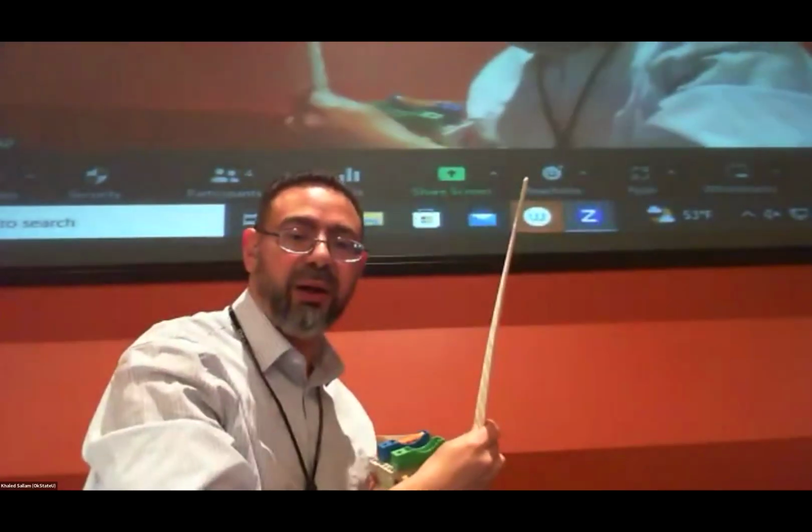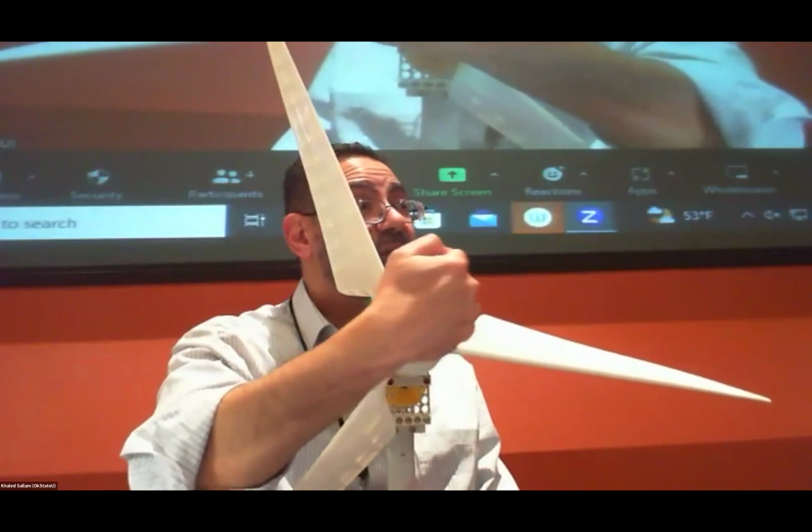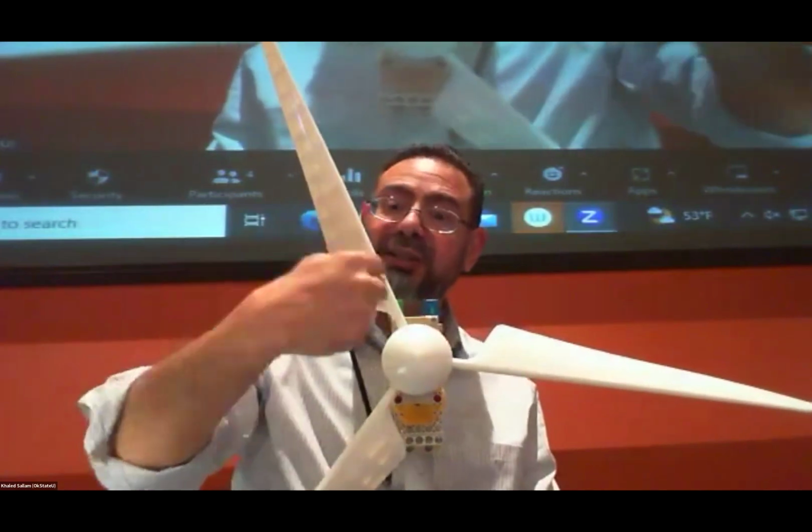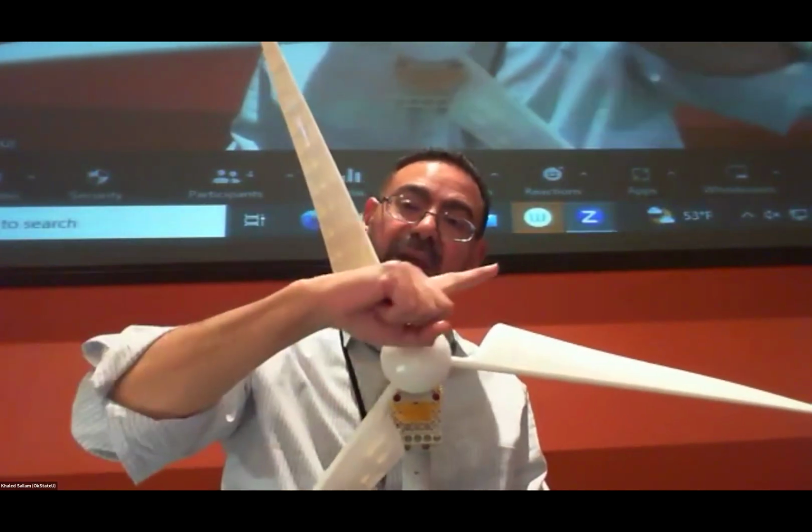And we remember how the plate is not twisted at exactly the same angle everywhere. Why? Because it's designed not for V absolute. The plate is designed for V relative. And why is V relative here in a different direction than this V relative? Yeah, U is different, right? So for the same V, U here is small, U here is big.